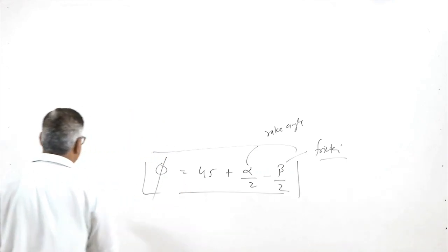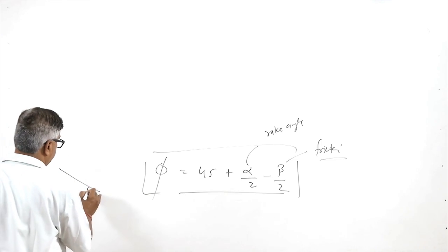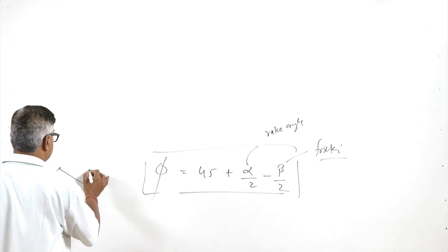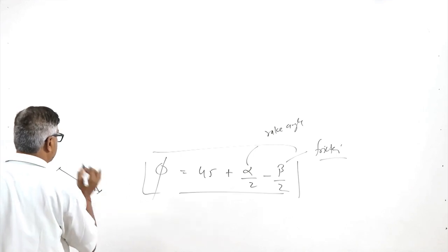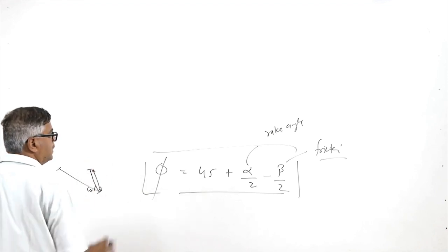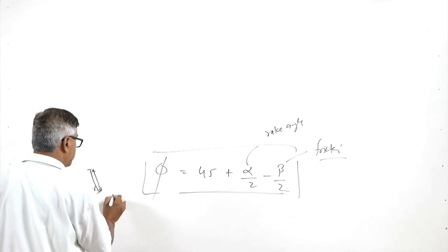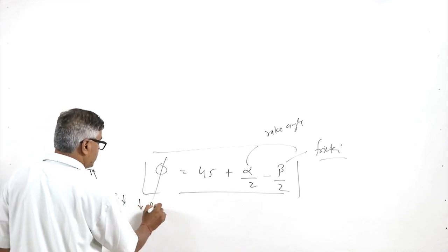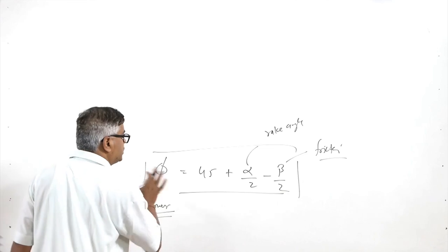As we have just seen, when the shear plane angle is low, the shear plane length is more under identical conditions as compared to when the shear plane angle is high. So, a high shear plane angle results in a lower shear plane length, and this in turn reduces the Fs value, and also reduces the power required for shearing.